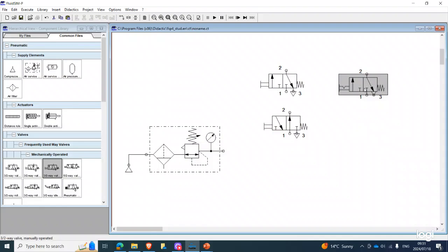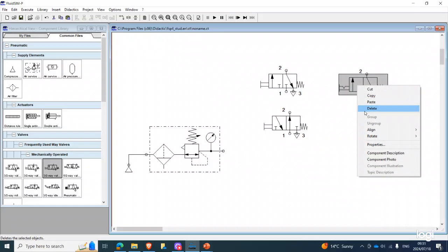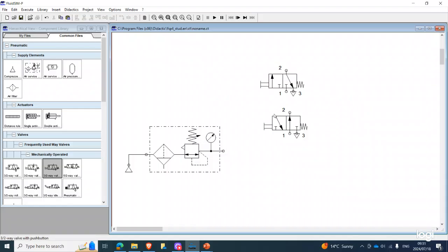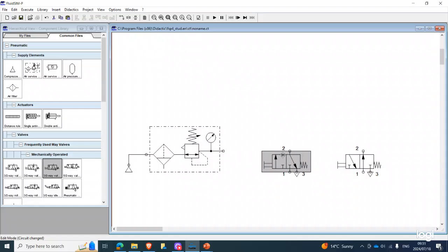And then this is a selector switch, right? The difference between a selector switch and these two is that the selector switch is latched, right? So we'll be covering it in a later exercise. So now, since we have these two, we have to choose which button we are going to use according to how they describe the process to us.